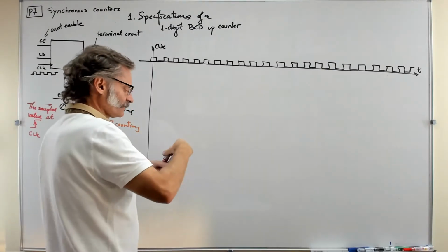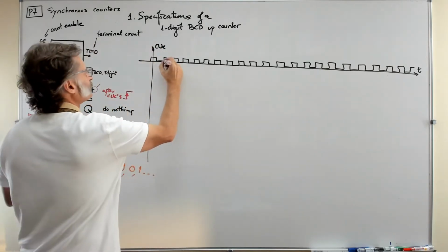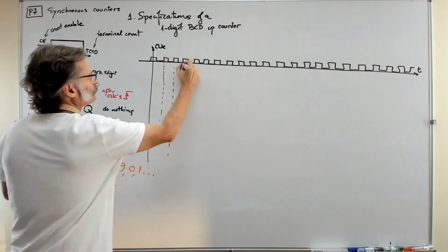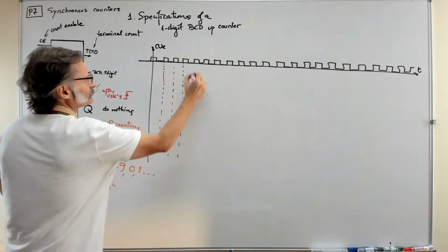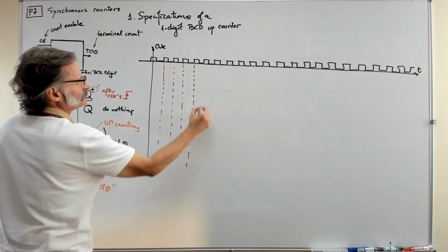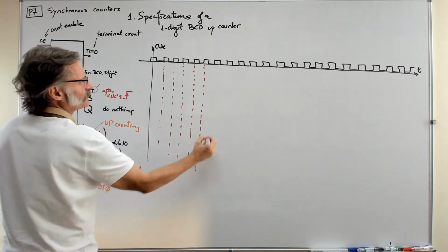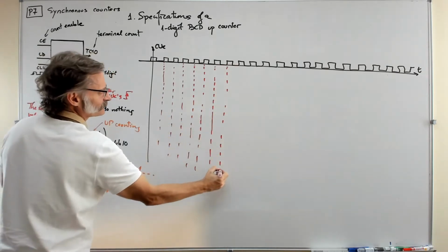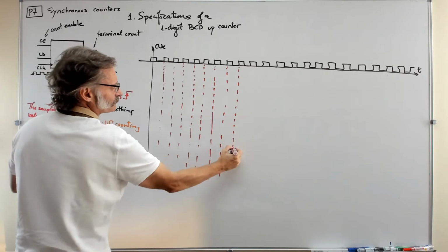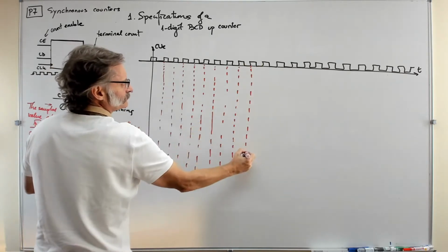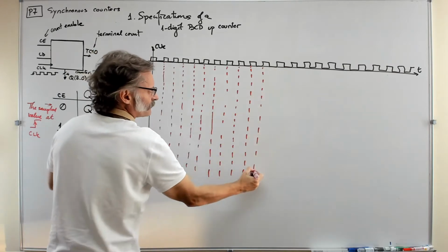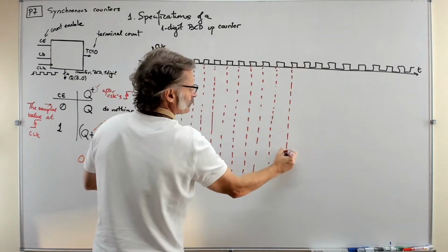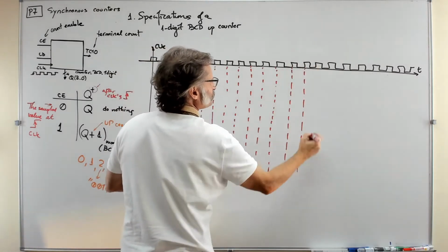And what goes next, again I have to insist on this, is the rising edge, because this is what is necessary to know very well. If the coded outputs in BCD have to be changing, that change is only possible after the rising edge of the clock, if you let the system go counting. So that is the idea. This is why you have to take a sheet of paper and mark in time the rising edge of every single clock pulse.